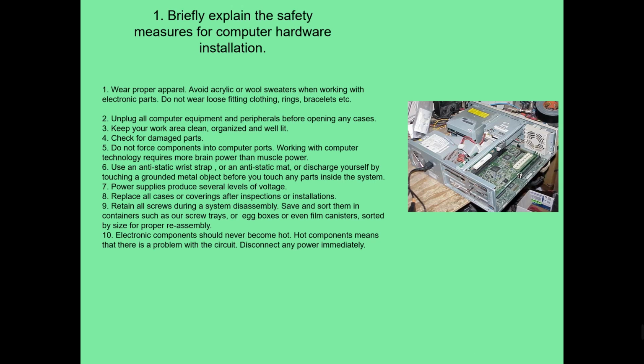6. Use an anti-static wrist strap or an anti-static mat. Discharge yourself by touching a grounded metal object before you touch any parts inside the system. 7. Power supplies produce several levels of voltage. 8. Replace all covers after repairs or inspection.